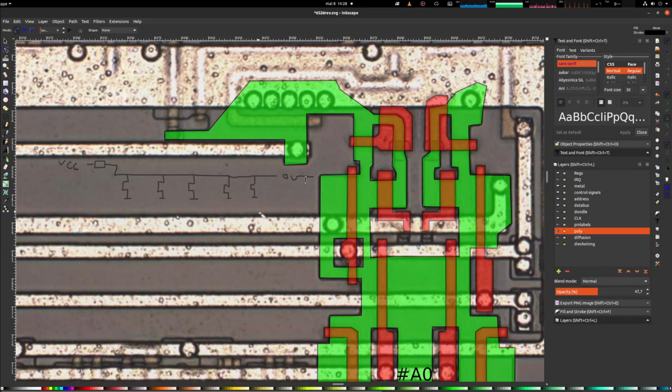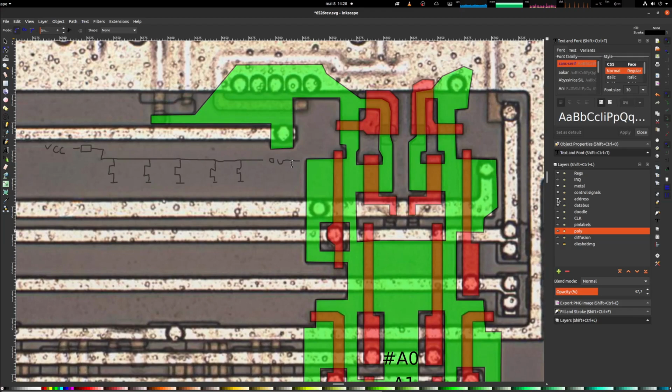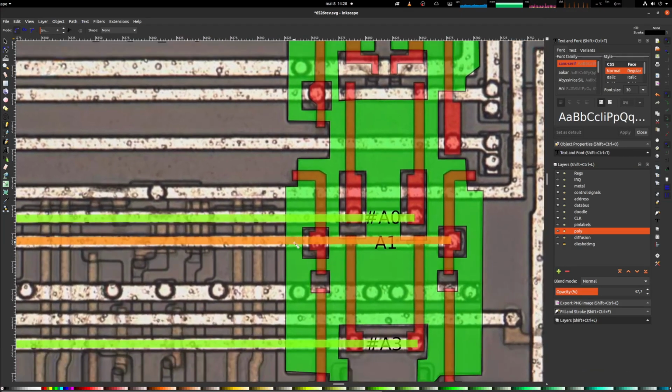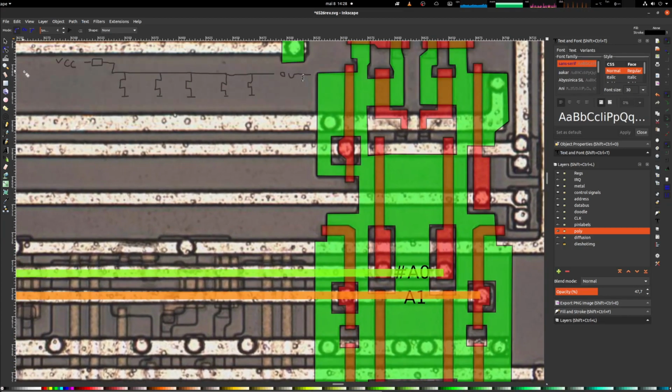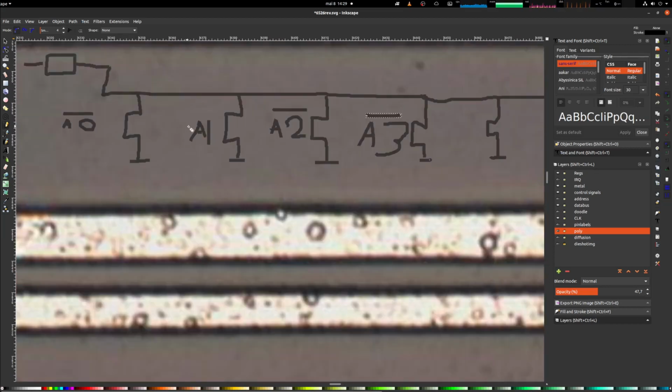And what's what here? Let's bring in the address. Okay, here's the address. And we see that the address line A0 is here. So you can actually say this is A0. If one of these is high, then the output will be low. So basically you have an OR gate, NOR gate, sorry. So this is the equation for that matter. And we can use De Morgan here.